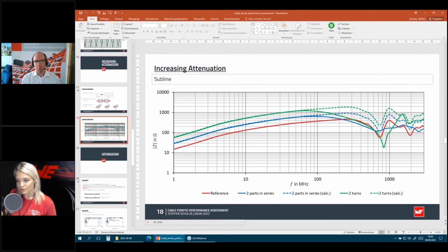If the core material was chosen properly, and the length and the diameter were chosen properly, then you already get a good result. If it's not enough, if you need some more decibels of attenuation to go below the limit line, then you need to perform some investigations, some shifting of the sleeve, and repeating the measurement.